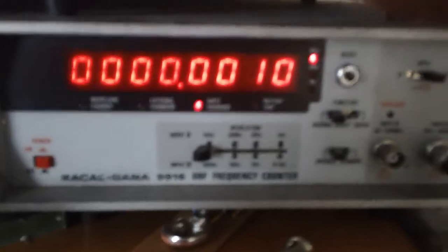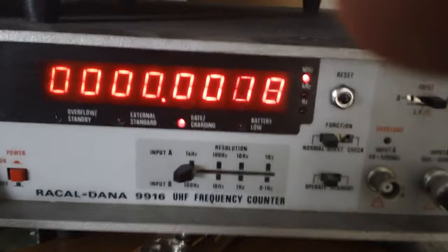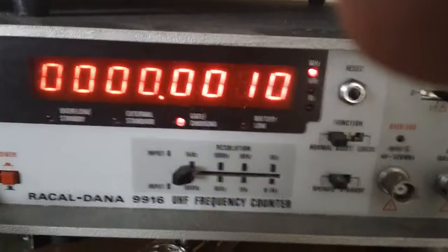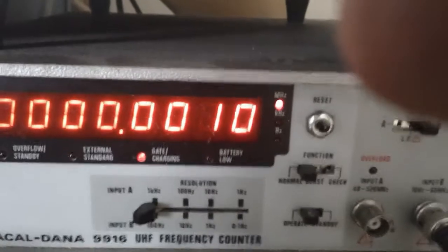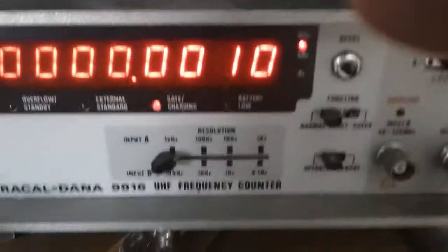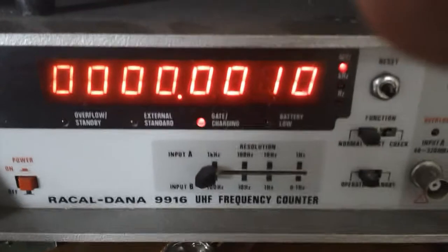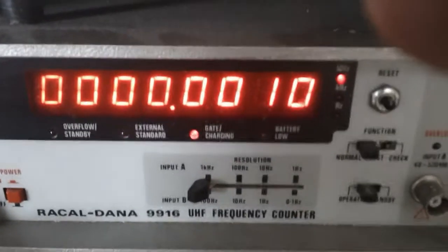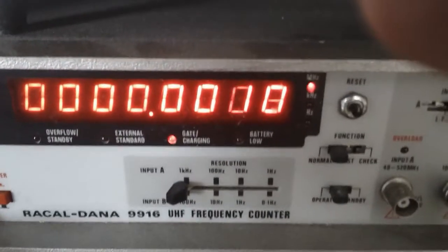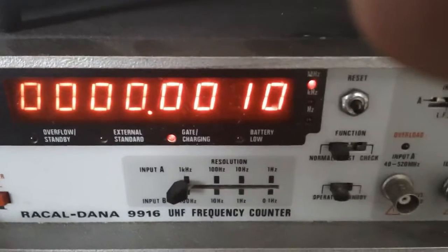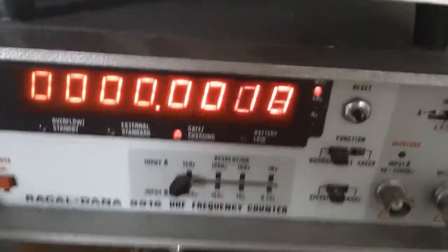And I thought I'd tidied my bench. Okay, on the right hand side, we've got my old and trusted Dana frequency counter. Gosh, I've had that a long time, and still working beautifully. I calibrated it a couple of weeks ago, and it's still bang on. How did I calibrate it? I calibrated it against WWV, which transmits on 10 megahertz. Dead easy to do if you know what you're doing. I'm sure you don't want to see my finger.